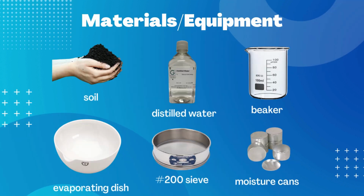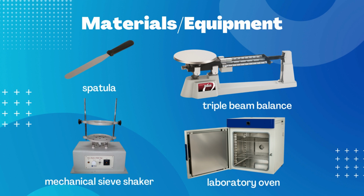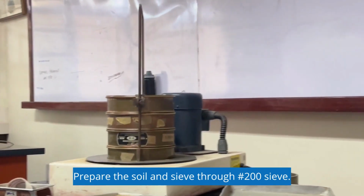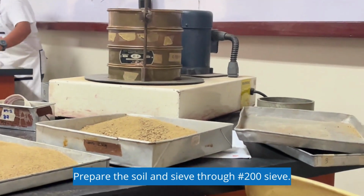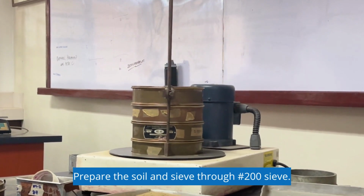The materials and lab equipment to be used are soil, distilled water, sieve number 200, beaker, 3 moisture cans, evaporating dish, spatula, triple beam balance, mechanical sieve shaker, and laboratory oven. We prepared the soil in the laboratory by crushing it in order to prepare it for sieving. We used the number 200 sieve and the sieving motor for sieving the soil, in which Sir Johan assisted us.